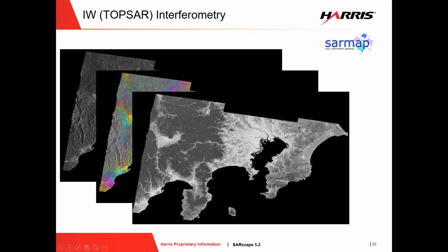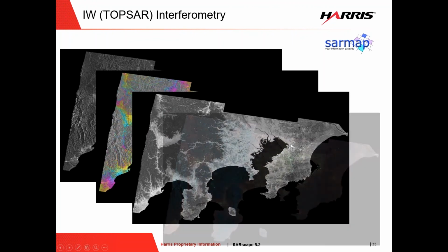And this is the corresponding coherence map. We see no discontinuity, the coherence is continuous through the subswaths. We see good coherence in white over the inhabited areas, lower coherence as expected, because we are speaking of C-band data over the densely vegetated area. Even with 12 days, we cannot forget the temporal decorrelation over forested areas.